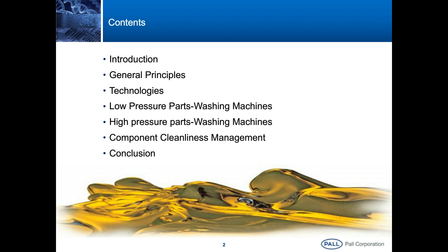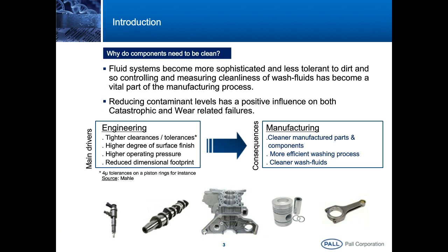So, why do we need to produce clean components? For the last decades, fluid power systems have been submitted to more and more technical challenges. Service pressures keep rising up, warm-up cycles are getting shorter, uptime requirements from end users are higher, etc. To respond to these changing market trends, component clearances and tolerances have continuously and dramatically reduced.